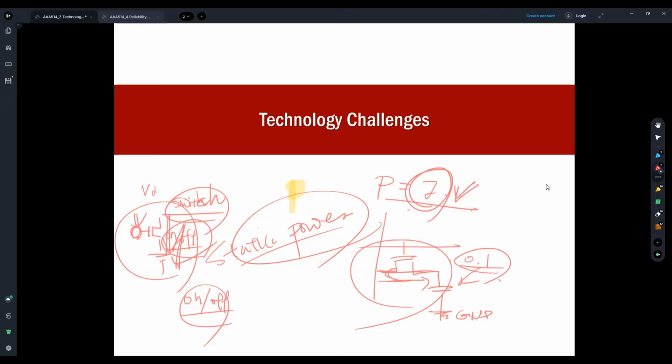And it's the same for the memory. So think of this DRAM. This is the CMOS transistor switch. Actually, not CMOS, it's an NMOS transistor switch. So we try to close this NMOS transistor with this word line, the voltage level, but the NMOS transistor is not entirely closed. So electric charges can be dissipated from this capacitor. It's a very small current, but the current flows through this NMOS transistor. Which means DRAM.